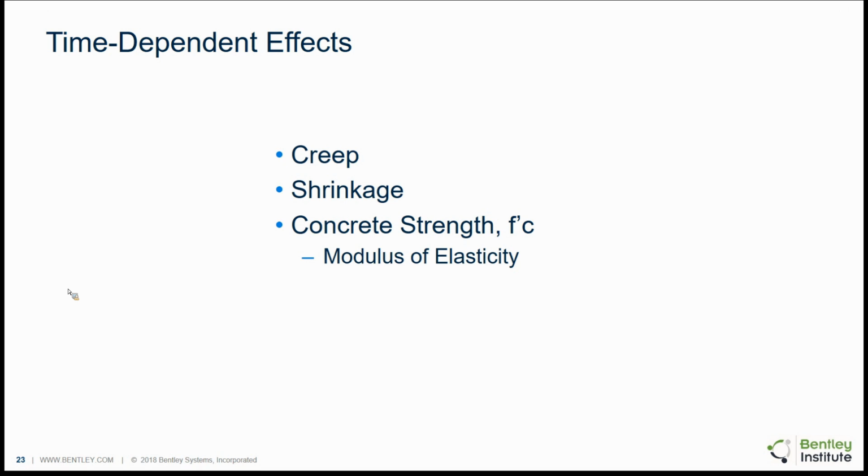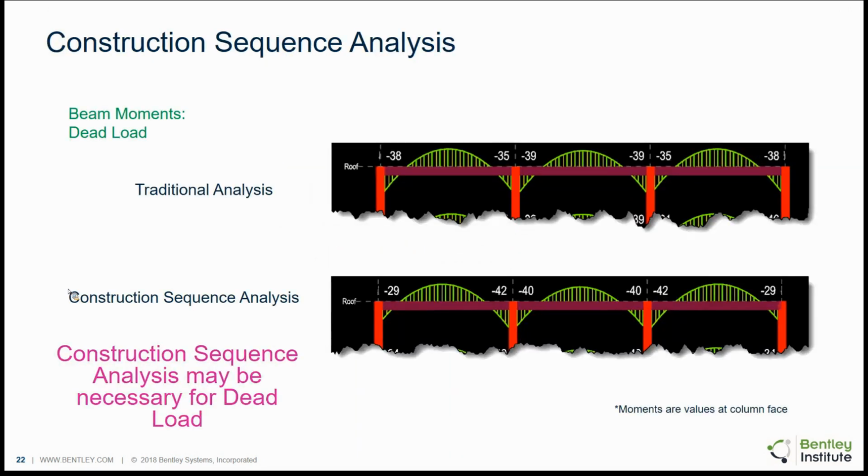Say, Alan, can I jump in here? Sure. A question came in regarding the last slide. The question was, unless the building is really tall, the effect of axial shortening should be too small for consideration. Is that correct? If you have a short building, that's the case. What we're looking at here is a 9-story building, and so you'd have to decide if that was enough for you to worry about. But certainly for the shorter buildings, 2, 3, 4 stories, probably not a problem.